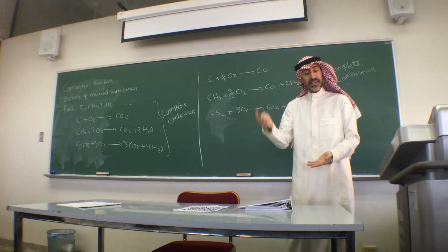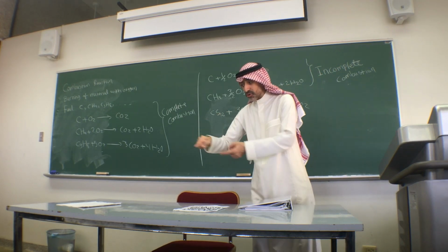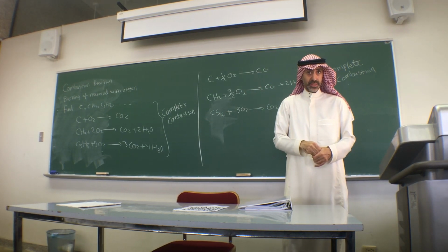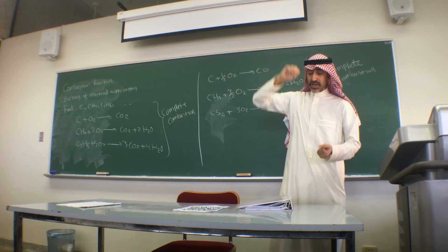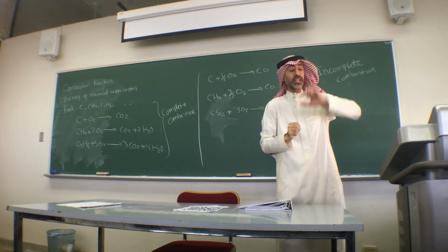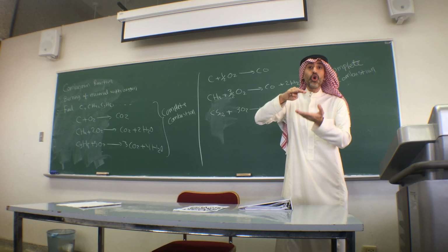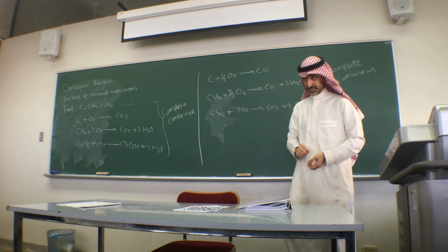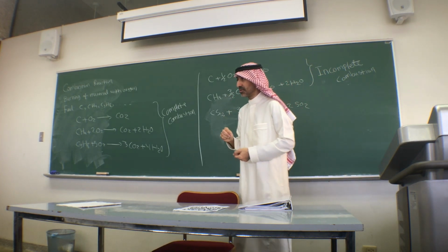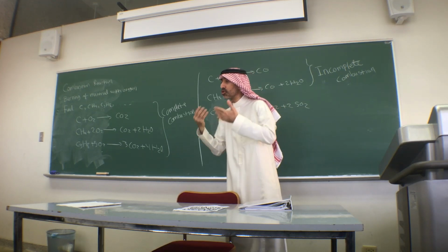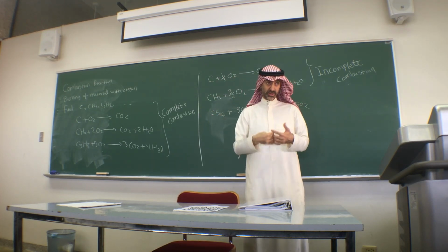Now, if I consider the water and calculate the total with the water and divide by that total, they call it wet basis. Why is it wet basis? Because I am considering the water.